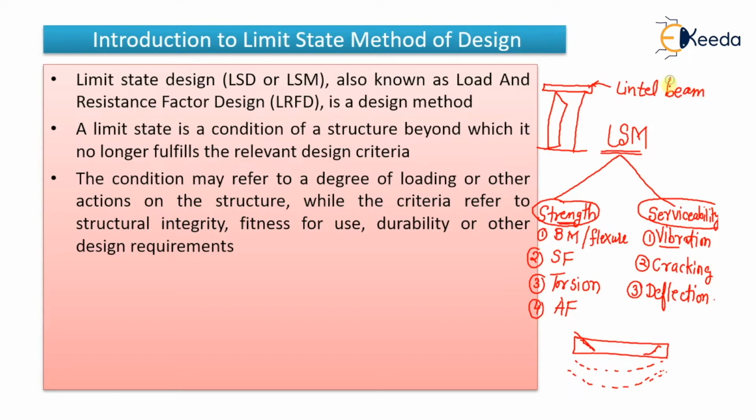Now, what my concern is, let us imagine, let us assume that this lintel beam got a certain degree of deflection. It got deflected like this, a very small amount, maybe 5 mm, 10 mm, 20 mm. Let us consider it is 20 mm deflected. This beam is deflected 20 mm, and because of that, this door is not getting closed. So tell me, is it safe or not?